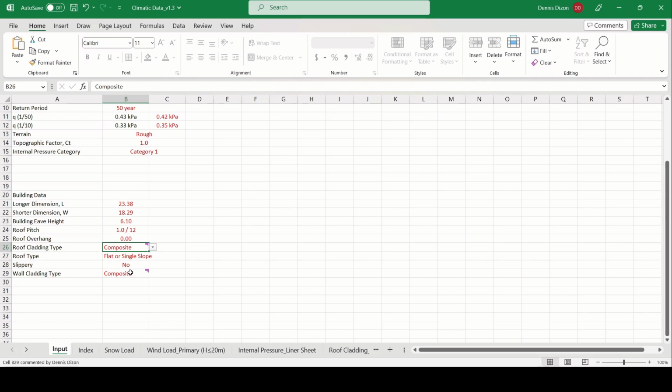So what I will do is a mock-up calculation of the frame itself, as if I'm the one designing the rigid frame, so I can get the reaction. I will do the analysis that the pre-engineered building supplier will do, like calculate for the dead load, live load, snow load, and then analyze the structure.